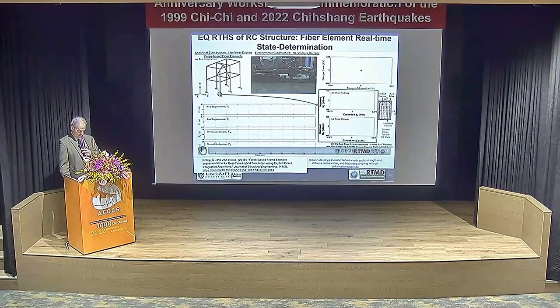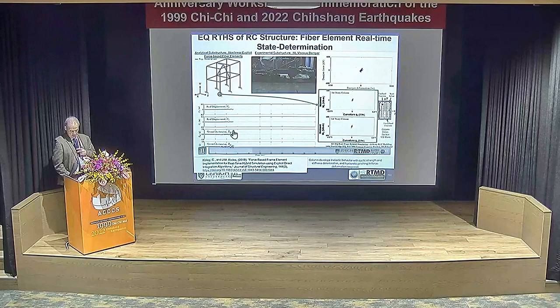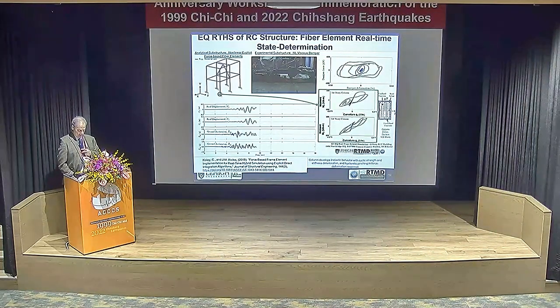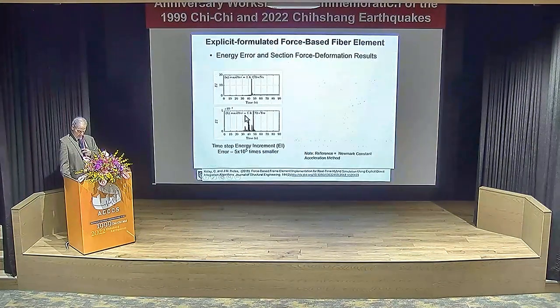And then this is how fast things have to go. This time step here, I think, was 2/1024. As you know, concrete, and this is bidirectional loading, I don't show the axial force, but that could have an effect, but it shows the deterioration, the stiffness, a little bit of pinching, and the energy dissipation. The upper right is the nonlinear viscous damper. Notice the force is capped, and that's going to be important when you design things. If that force kept increasing, you could have problems with the adjacent members.